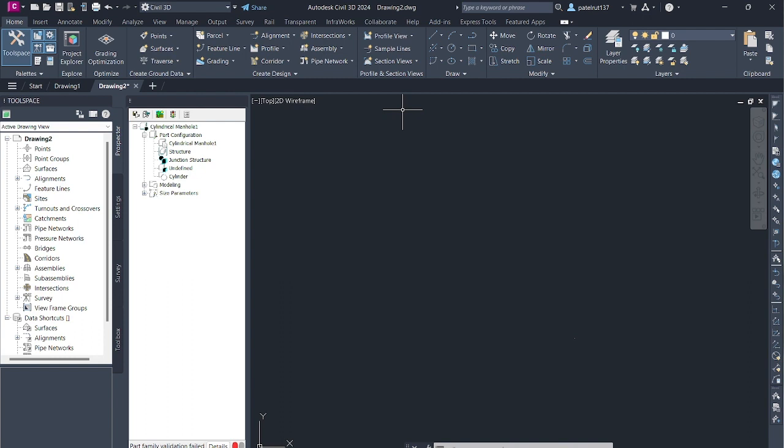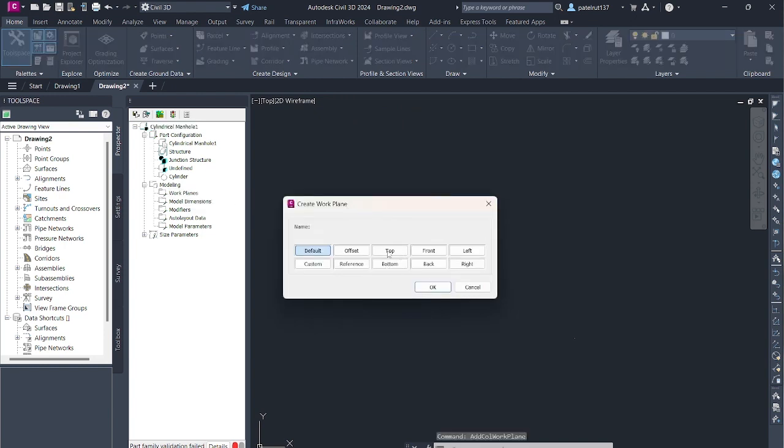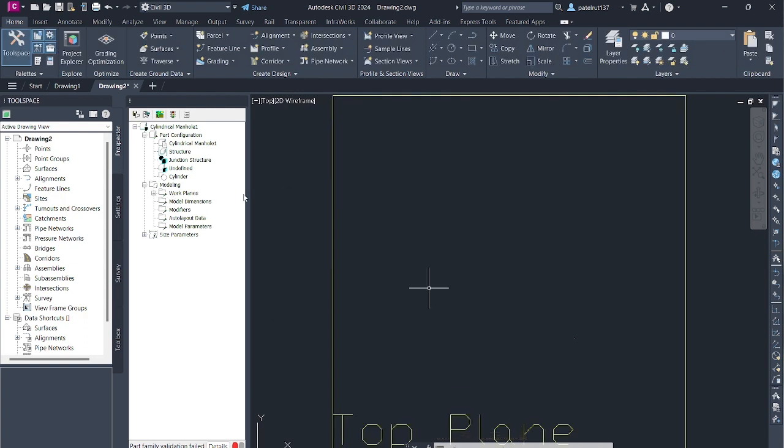In the Edit Part Sizes dialog box, click New to display the new parameter dialog box. Add the following additional parameters using the new parameter dialog box. Structure Riser Height 2. Inner Structure Diameter. Frame Diameter. Frame Height. Cone Height. Slab Thickness. Barrel Height. Barrel Pipe Clearance. Each new parameter is displayed in the Edit Part Sizes dialog box.